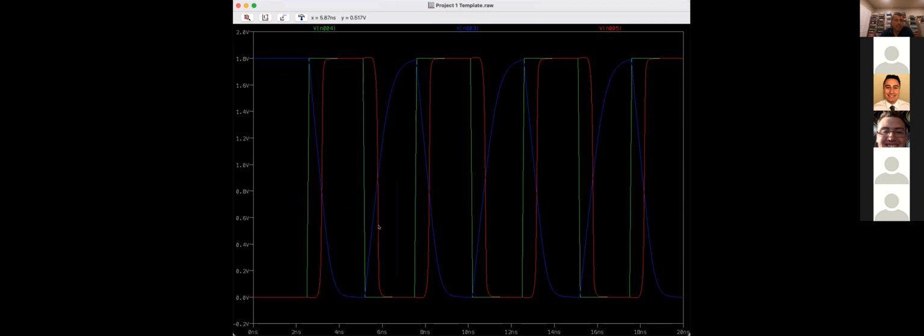It's sort of getting to the full value, but it's really questionable, right? It's kind of just touching 1.8 volts barely. Looks like the fall time is still pretty good. A zero value stays zero for a pretty good while, but the one value is not valid for long enough.